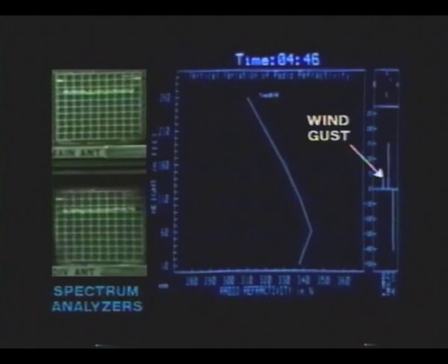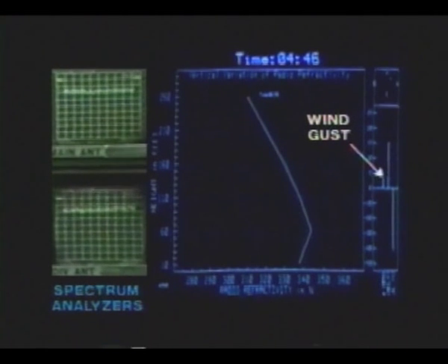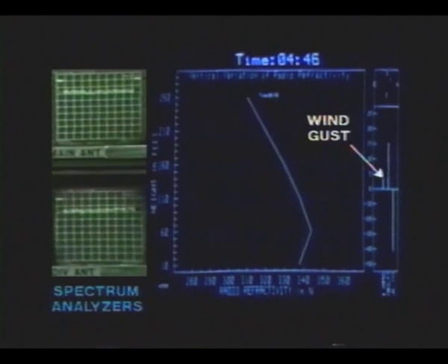Let's pause for a moment to take a closer look at this event. Shortly after 4:30, the wind begins to blow from the northwest. This moves the stratified air masses, which were formed in the past during the period of no wind, across the sensors mounted on the Kaufman Tower. This movement allows us to see the super-refractive condition, which has been causing flat fading of 20 to 25 dB